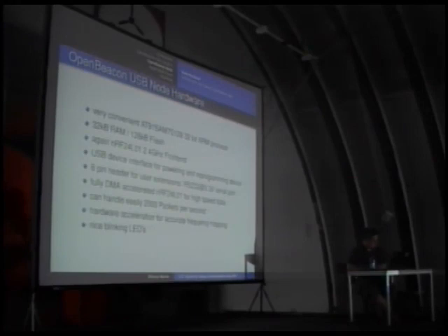If you want to use it to extend your hardware, you have an RS-232 serial port. We implemented full DMA acceleration, so you can download the data from the nRF at full speed. It doesn't block the CPU. Meanwhile, you can do different tasks. It can easily handle 2,000 packets a second, and it already has support for hardware acceleration for frequency hopping.